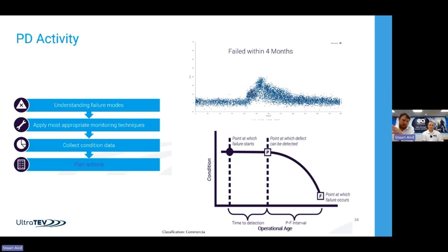So it was our first round of measurements on this site. So unfortunately, we can't show what would have been 12 months ago. But from detecting activity of that sort of magnitude and repetition rate on that type of transformer, we've then seen a failure within 4 months. So planning your actions and, importantly, surveying regularly enough to give yourself time to act is key. And bear in mind that surface activity will generally tend to failure a lot quicker than any internal void or internal activity. So in general, you should be reacting quicker to surface activity.